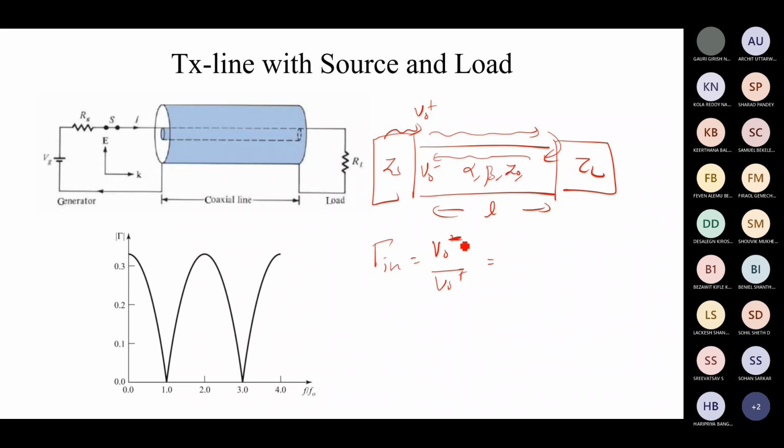By measuring this, we can say whether the source and the load are in the maximum power condition or not. When it is zero, this is often referred to as matched. When it is equal to 1, that is mismatched. And when it is greater than 0 and less than 1, they are partially matched. So this describes the maximum power transfer effect using these transmission lines.